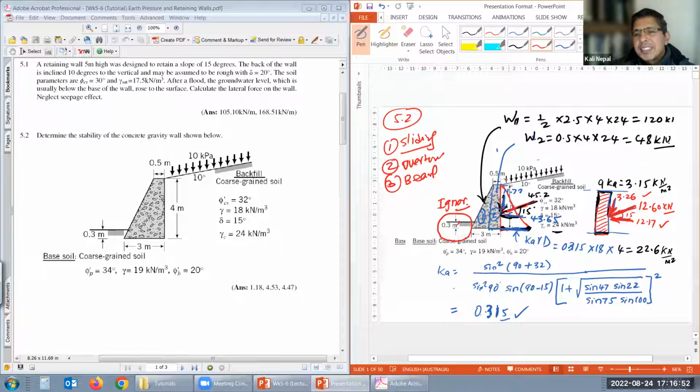It will be safer if you ignore the passive pressure. You can calculate it, but that is not necessary as long as it's small. But if this part is very high, then we need to calculate it. Who makes a wall putting backfill on both sides? That's not that common, so just ignore that part.